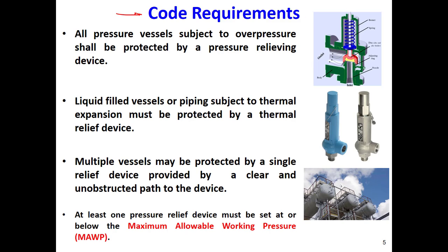We have to consider what the possible scenarios are in which we need this kind of valve, what are the possible scenarios in which we might have some excess pressure in the system, and how much will be, in the worst case, that excess pressure that we have to relieve, right? So based on all this information we have to choose and pick the right relief valve.